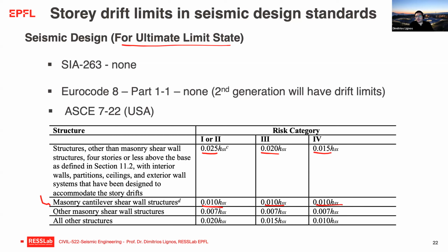And of course, if you have structures that fall into different categories, again, you have to group them and decide what would be the drift limit to consider for seismic design with specific story drift limits.